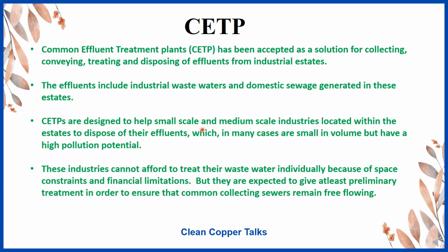CETPs are designed to help small scale and medium scale industries located within the estates to dispose of their effluents, which in many cases are small in volume but have a high pollution potential. These industries cannot afford to treat their wastewater individually because of constraints and other limitations, but they are expected to give at least preliminary treatment in order to ensure that the common collecting sewers may remain free flowing.